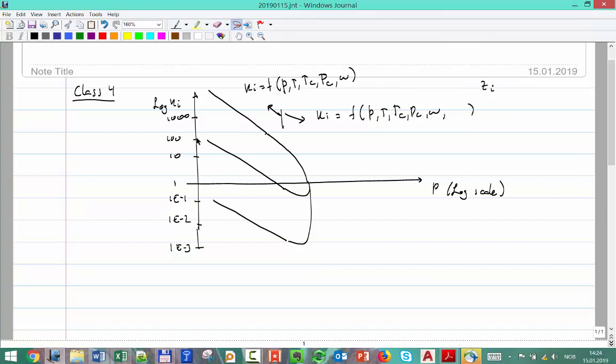We know it depends on that, but we create this fictitious pK, this convergence pressure, to try to capture that effect. And practically, you can change that number until you get a match with the data. So pK is representing the composition dependence.